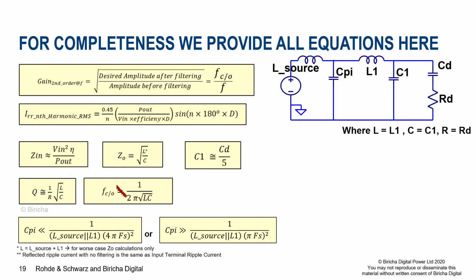So then we had a bunch of other equations which are given around here. That is the standard equation for working out the cutoff frequency, which is 1/(2π√(LC)). But we said that unless we limit our choices because of our constraints, you effectively have a huge choice. At that point, we used an impedance paper, and we used various constraints.